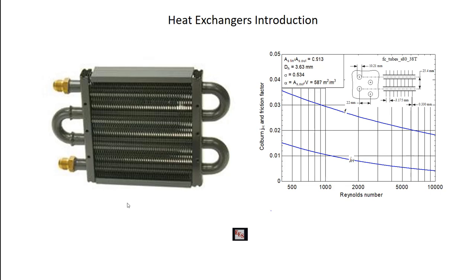All right, so that's an introduction to heat exchangers, the different configurations, what fouling means, and then at least an introduction to some of the ways that you might have to go get the UA, the conductance. What we need to do next is start looking at, okay, I have a heat exchanger, I know the conductance, right? I figured it out, I know the overall energy balance. I got to dive in now and actually do a differential energy balance on each of the two streams and solve that resulting set of coupled differential equations, right? It could be coupled ordinary differential equations, right?